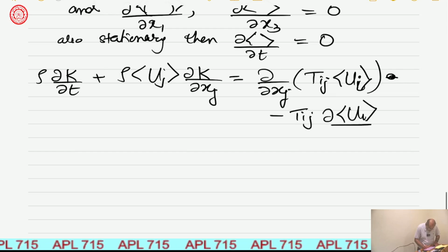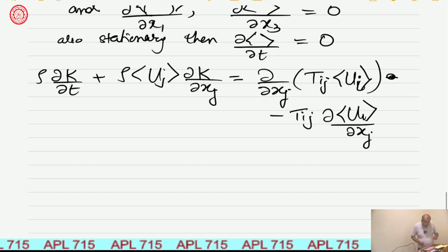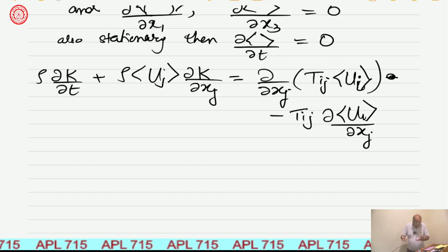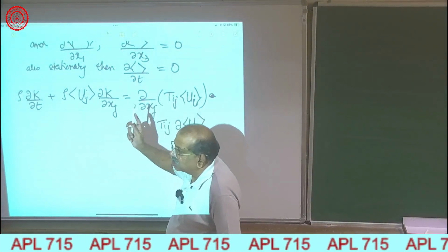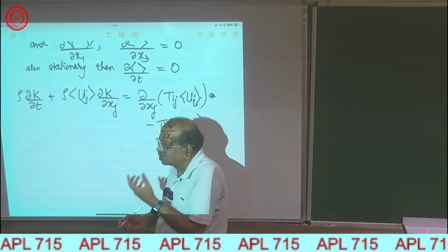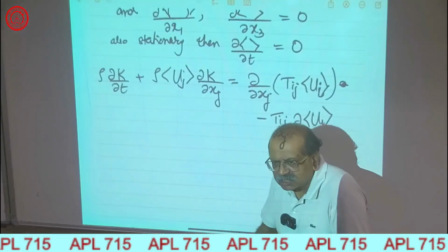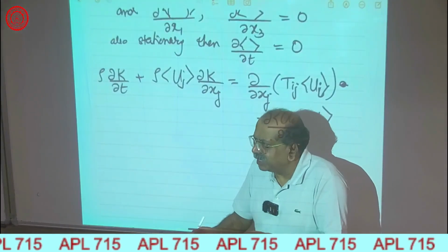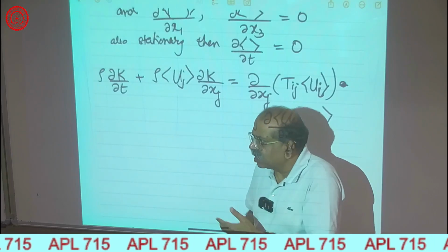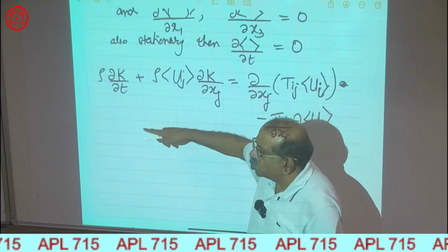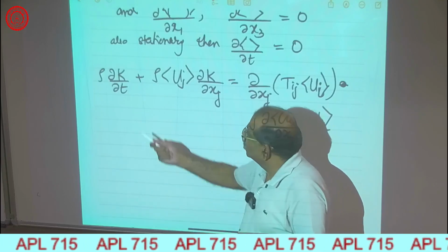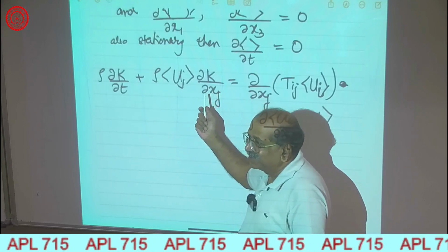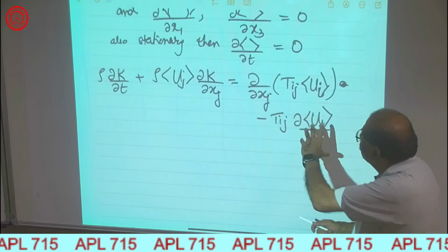I've just copied that equation. Now, how do we expand this? One thing I have often seen when I ask people to expand the energy equation, or this mean energy equation, is that it is quite straightforward. But even when I ask students to expand the turbulent kinetic energy equation and write the components, people write one component, two component, and three component. That is wrong, because this is an equation for a scalar. Each of these terms is a scalar.